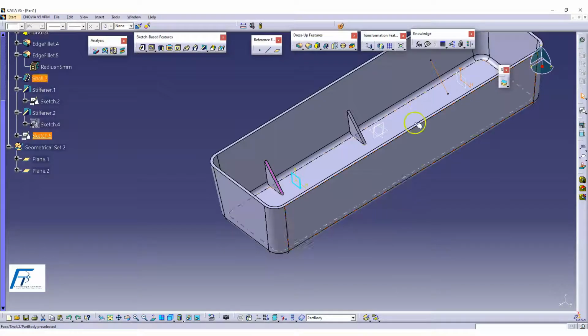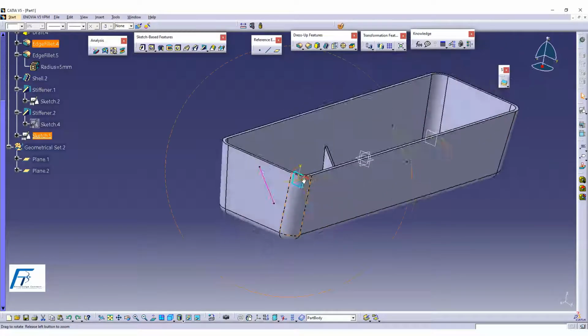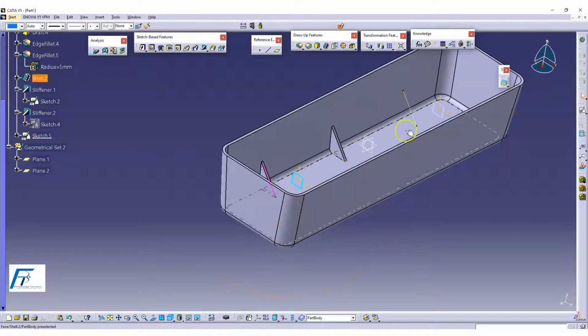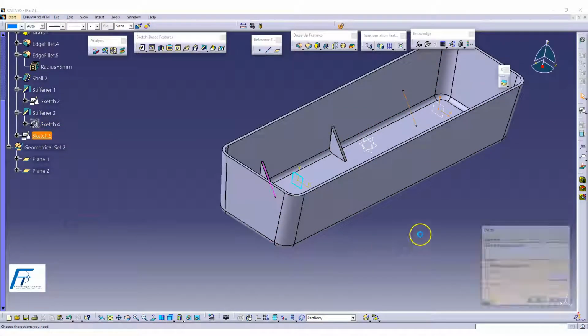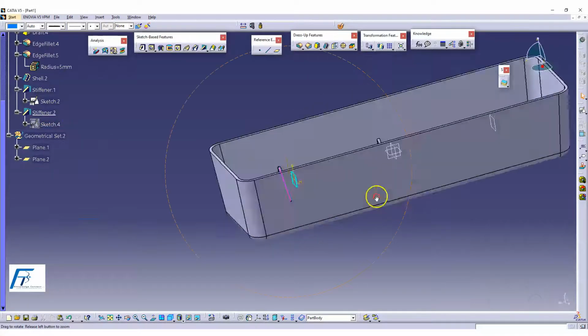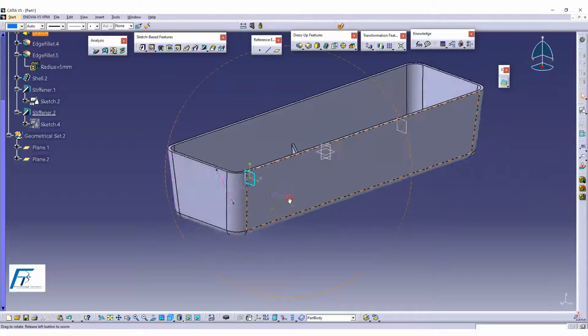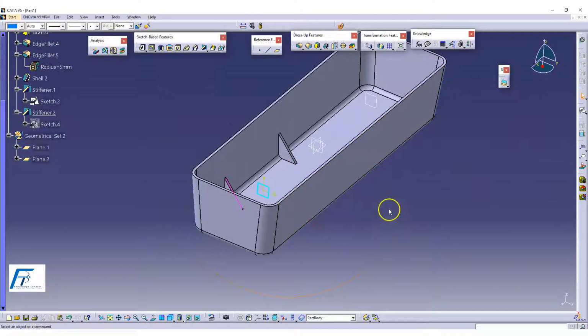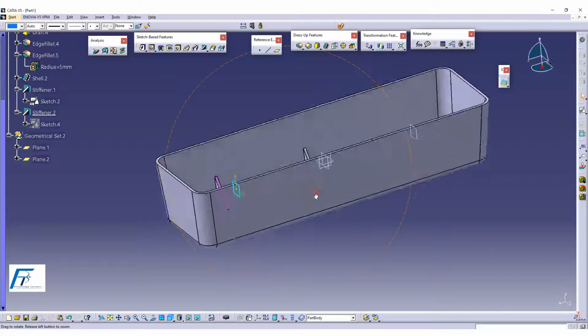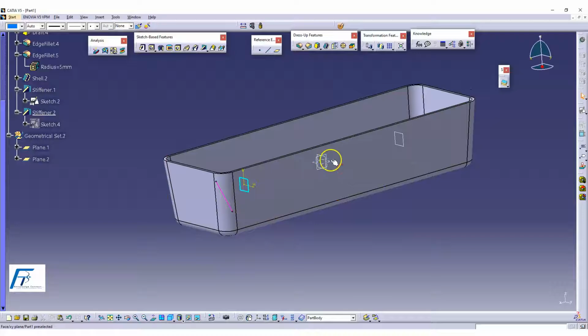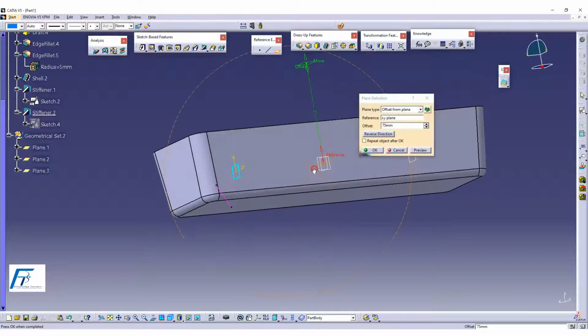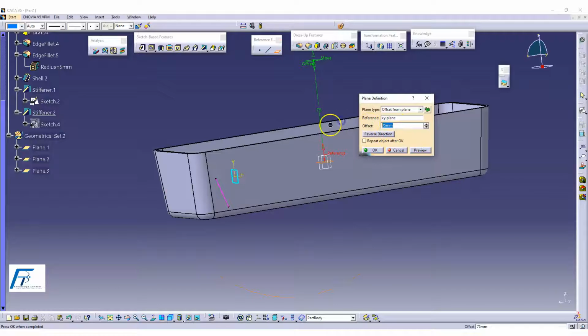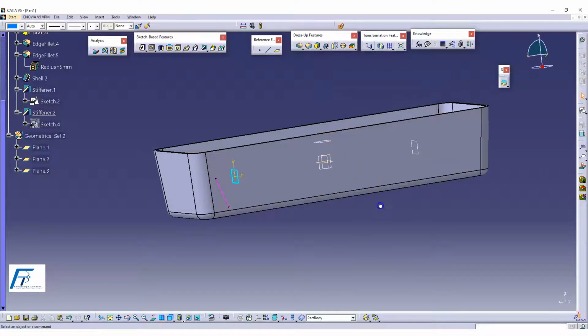Perfect. Thank you very much. So now what is our objective? Next I'm going to teach you the same fillet. So I'm going to delete this one. And I'm going to teach you fillet from top. For fillet from top, I'm going to just select a plane, and I see that this plane is at a distance of say for example 20 mm, 15 mm. Give it OK, you get this one.